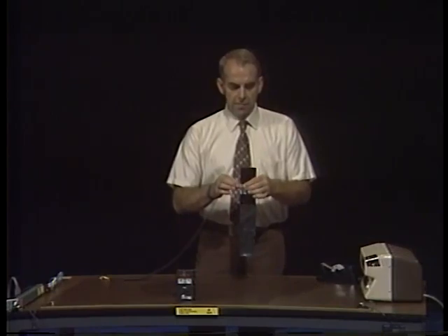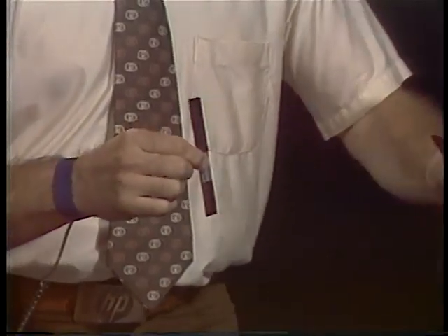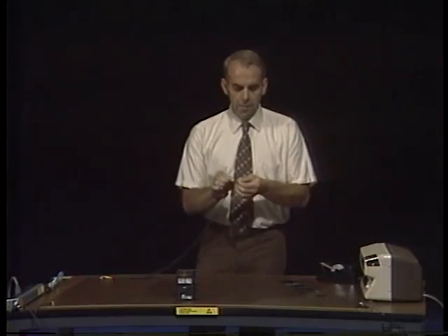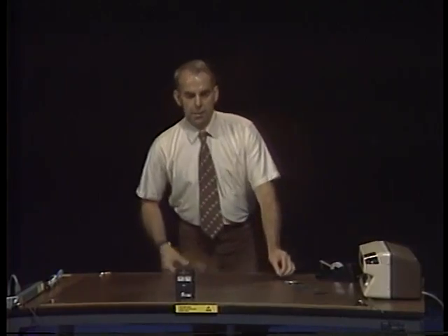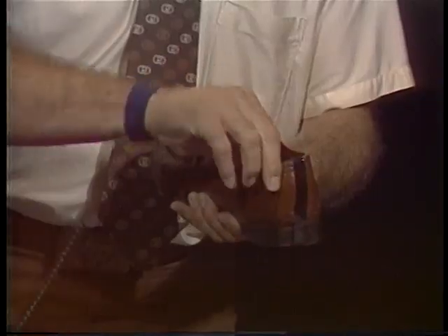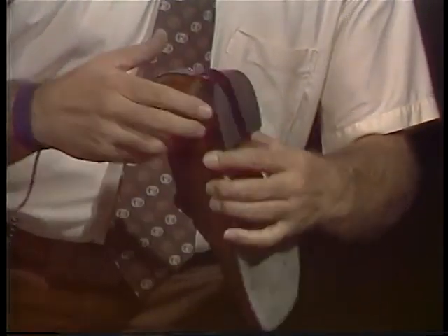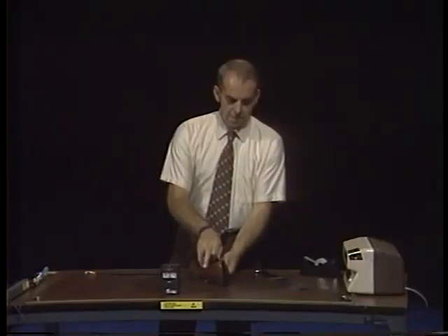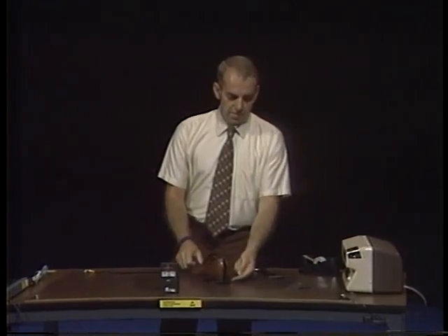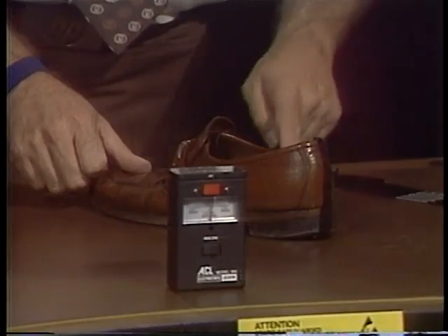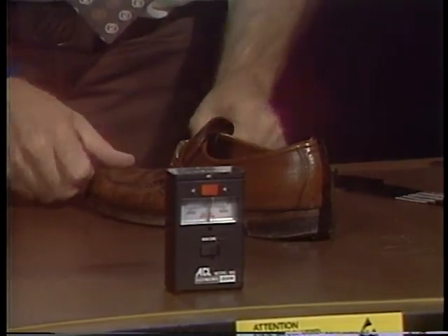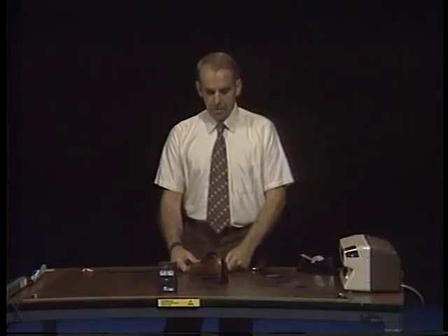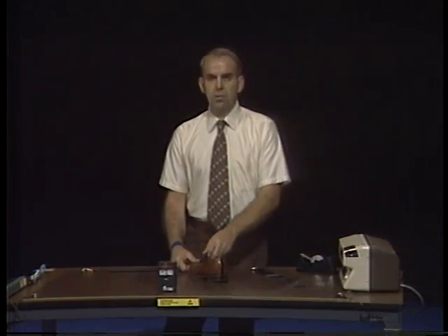Here is a sheet of 5 of these. To use them, you tear off one, fold it in the middle, place the shorter end down inside a shoe, around the edge, and put the part with the adhesive on the sole. Then when I step down on the table mat, there is a direct path through the strap to my foot inside of the shoe. There is enough perspiration in stockings to provide a good path from your body to this strap.